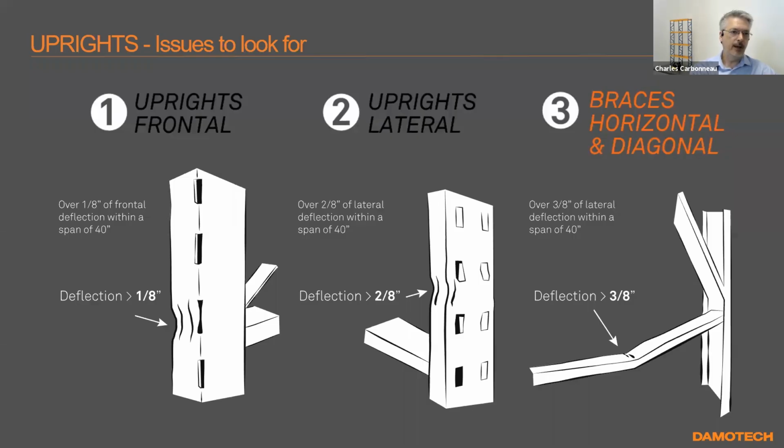Now, in terms of impact on the columns, what is the tolerance? What do we tolerate? This is not by code. By the way, the engineering codes never say how much damage is too much. They say basically, if it's damaged, unload it. But you realize, as soon as you see a little dent, unload the whole thing? There's a reality you have to address.